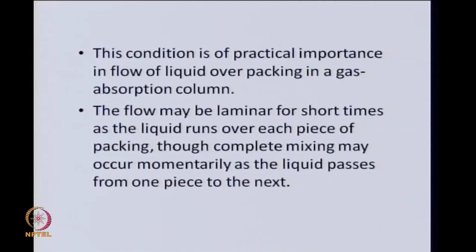Such conditions of short time exposure are actually important in practical situations like in gas absorption columns. For example, in a gas absorption column you will have packings, tower packings. Each piece of packing will have liquid flowing over it and the gas going through the interstitial space.